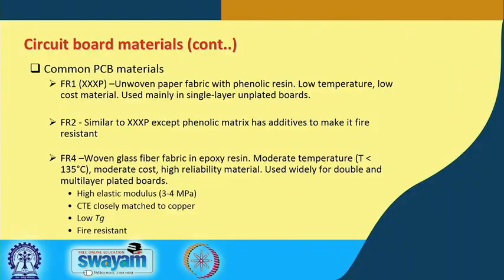Think about it, a motherboard is bending and then you have, let us say, a ball grid array package on top of it. What will happen? It is going to give a lot of stress to the solder balls in the ball grid array package, and some of those solder balls can crack and connections may be broken, and it can lead to complete failure of your product.